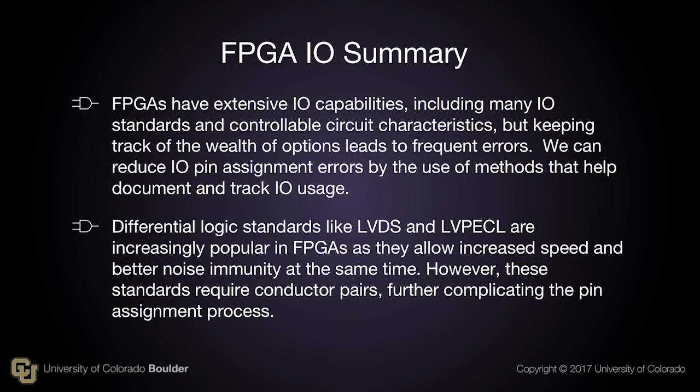Summarizing what we've covered about FPGA I/O, FPGAs have extensive I/O capabilities, including many I/O standards and controllable circuit characteristics, but keeping track of the wealth of options leads to frequent errors. We can reduce I/O pin assignment errors by the use of methods that help document and track I/O usage. Differential logic standards like LVDS and LVPECL are increasingly popular in FPGAs, as they allow increased speed and better noise immunity at the same time. However, these standards require conductor pairs, further complicating the pin assignment process.